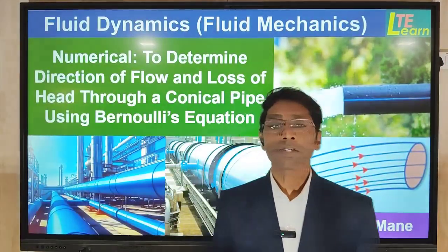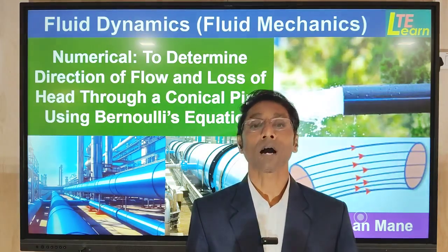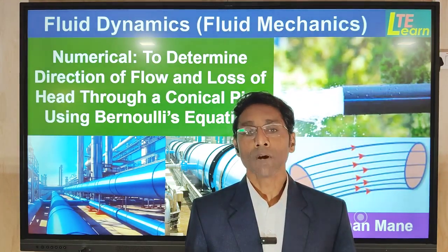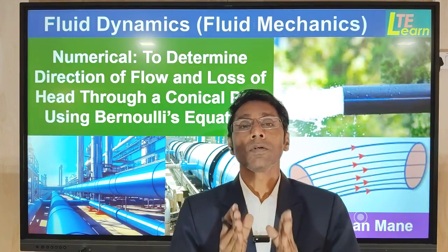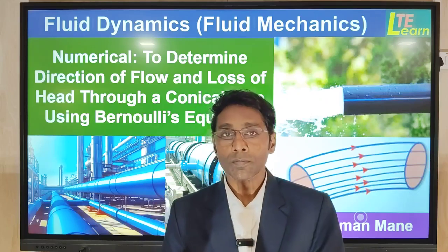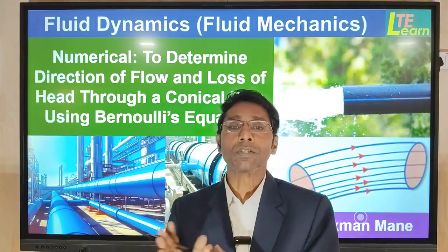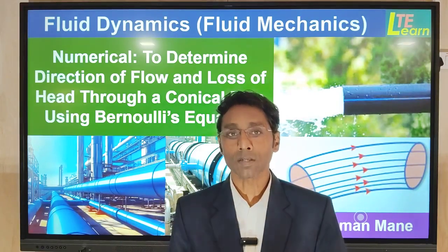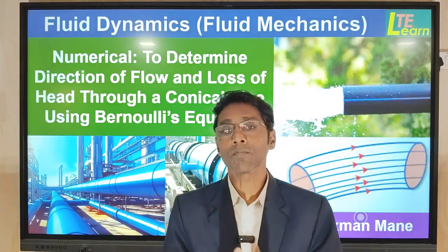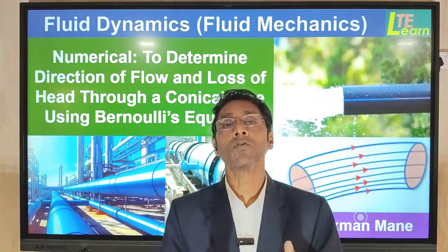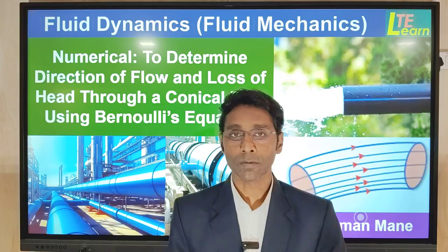In the last video session we have seen a numerical based on Bernoulli's equation for ideal fluid, in which there is no friction. Ideal fluid means a frictionless fluid. So in such cases there are no losses considered. But in the case of real fluid, loss of head takes place due to friction of the fluid with the pipe material when the fluid is passing through the passage.